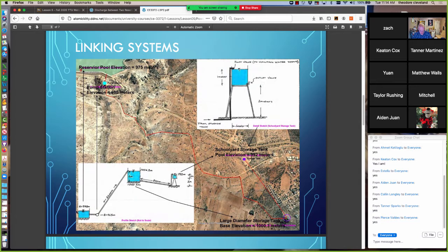Where the cursor is circling now is Lake Gulameta, and it's delivering into a pump, and that pump is pushing in a pipeline that's roughly 3,200 meters long. That's 3.2 kilometers of HDPE. It was laid by Texas Tech students working with the village authority here to make that first connection. And then there's a tank on the hill that's already there, left over from prior times, and the water's discharged in the top of that, and it can fill up to 6 meters.